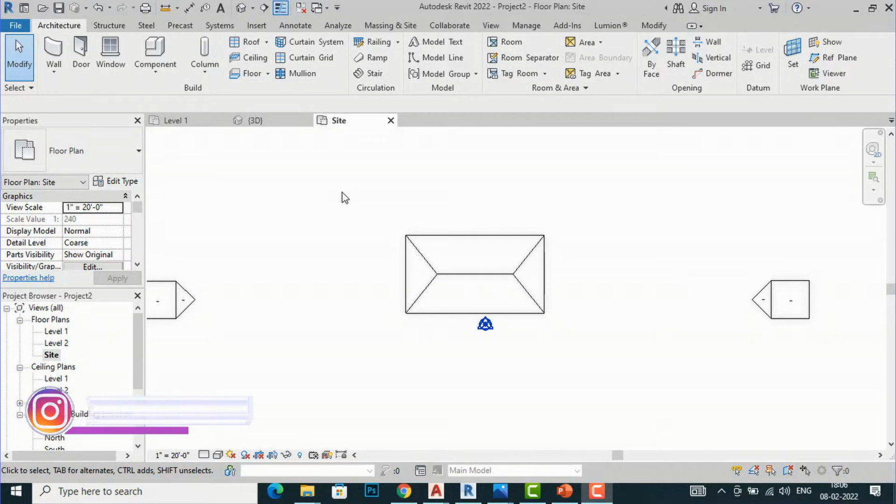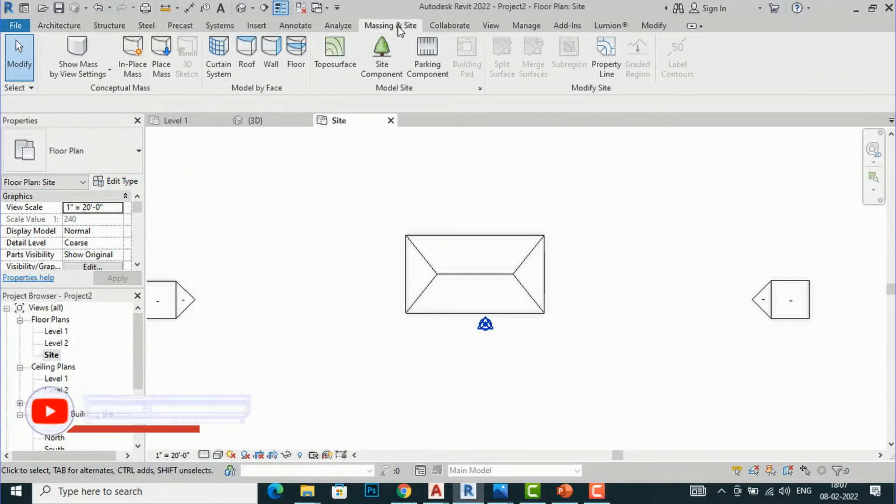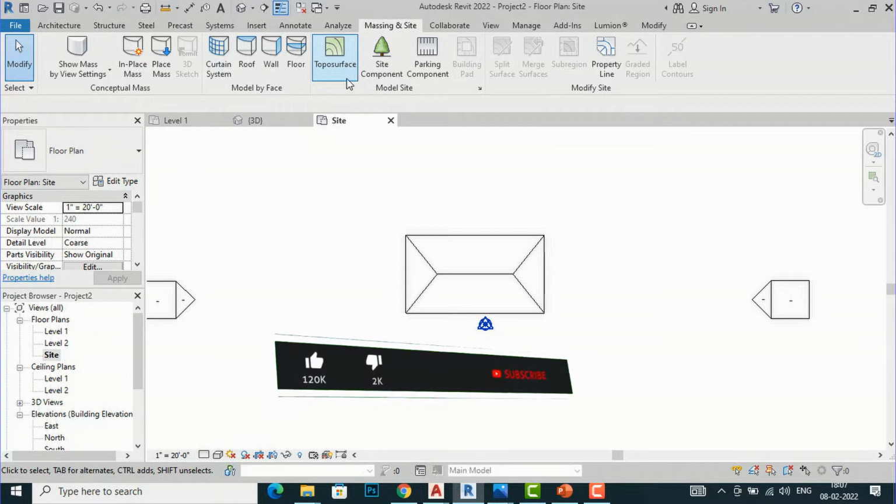In this video tutorial I am going to teach you about Toposurface in Revit. If you go to your Massing and Site tab and click here, you can see this tool Toposurface. It is generally used to draw topography in your Revit project.